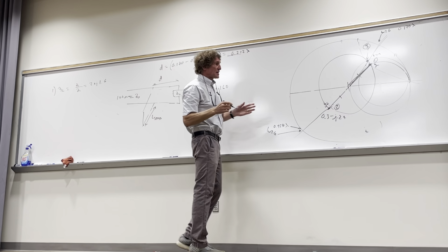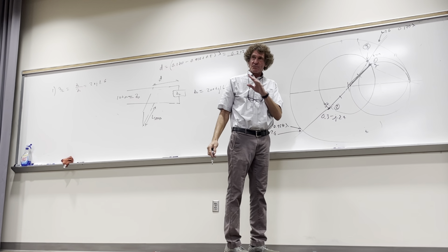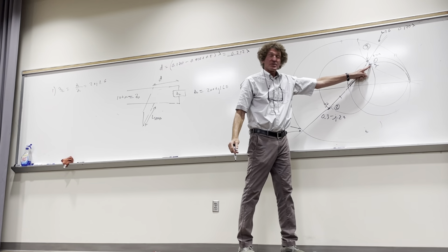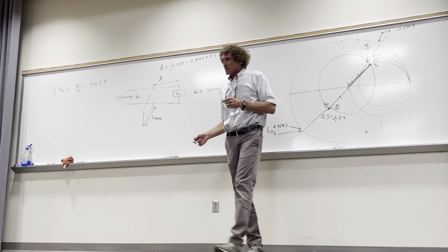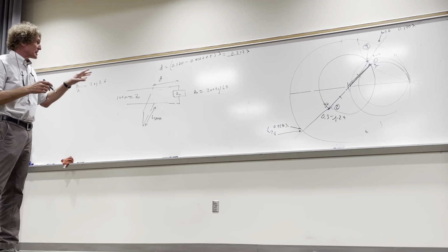0.212 lambda. The reason I said that, I know every time I move all the way around the circle back to the same point, I travel exactly a half wavelength. When I move half the circle, which is about there, it's a quarter wavelength, it's just shy of a quarter wavelength. All right? So, that checks boxes, that makes sense.